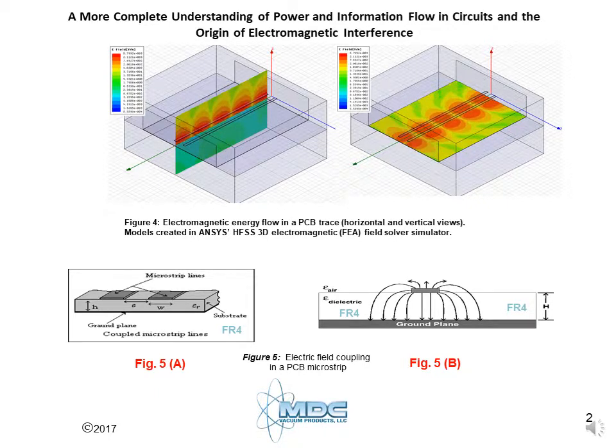One final point about the microstrip model. Two traces are used in most modern high-speed communication circuits. Digital data is sent along both traces, and the signals are compared and checked for errors. If an error, called a bit error, is discovered, that is, if a 0 is detected and should have been a 1, then the data is resent. This technique is known as Hamming bit error detection and correction.